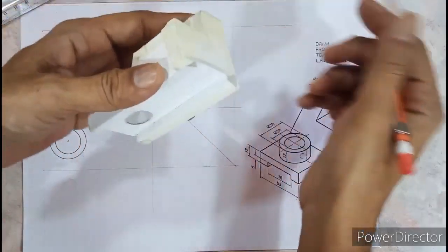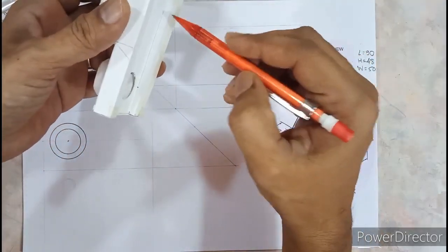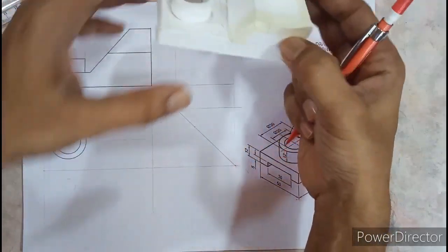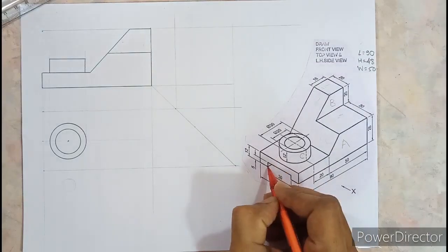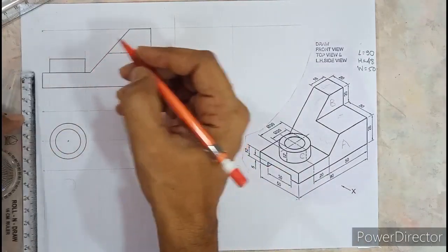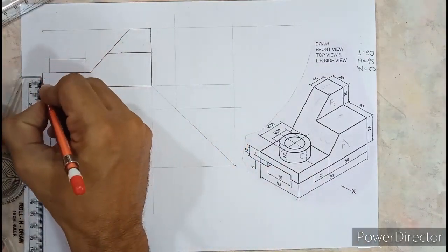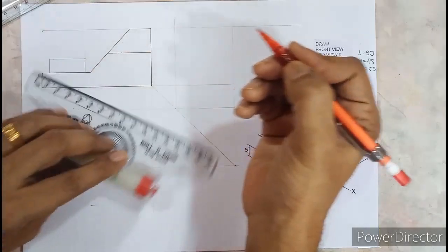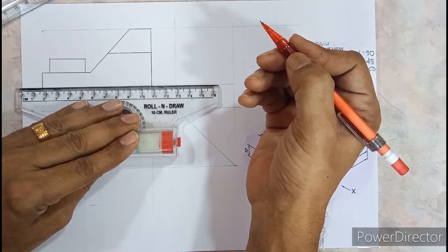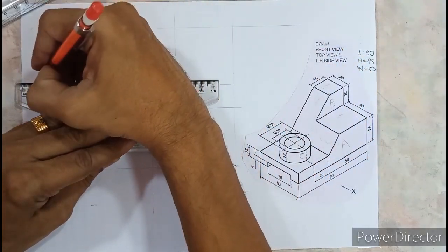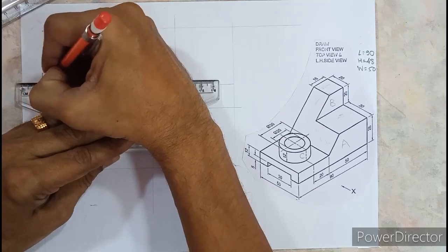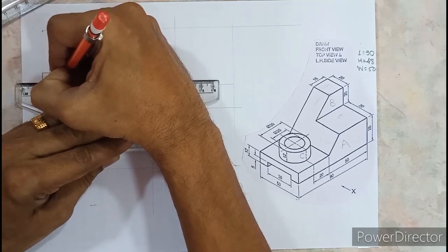Okay, so you cannot see this slot. So this slot you cannot see from the side. And that is 5 millimeter above. So that represents a hidden surface. You have to mark 5 millimeter here. Align the scale. And neatly you have to draw the cutout now. So you know that you have to double trace, because hidden lines should always be double traced.